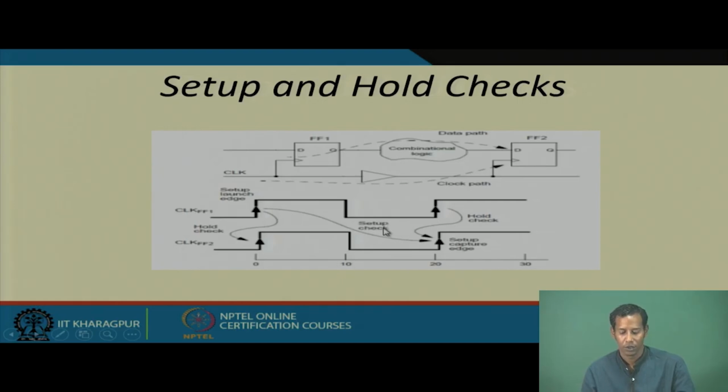Okay. So, this is the setup and hold check at this particular edge. You have to consider the hold check as well as the setup check for both flip flop 1 and flip flop 2.